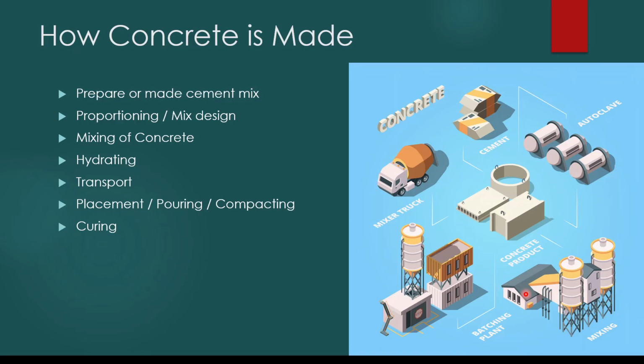Once you mix the concrete, we load it into the truck mixer. Then we transport it to the site. At the site we check the slump, and also we take samples to test the strength. So maybe cubes or maybe cylinders you test at the site. Once you have checked the sample is within the limit and taken the cubes for testing from that sample, what we do next is pour the concrete into the slab or whatever the element.